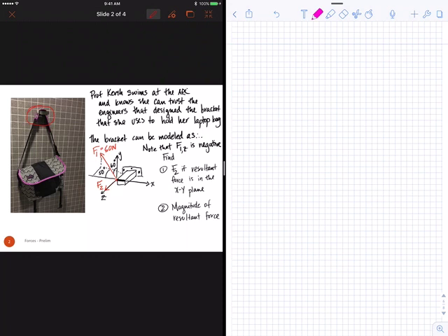I've taken off that front bit to show that what if I put my bag on there a little bit wonky so that it was only acting with a force at that one edge, specifically this edge right here, drawing on the PowerPoint slide. And so what I'm asking is, given this incredibly heavy bag and the angles shown, and note here that the z component of F1 is in the negative, find F2, the resultant force. What I want is the resultant force to be in the xy plane. So I don't want any forces coming out that might pull this thing out of the wall, and the magnitude of the resultant force. Okay.